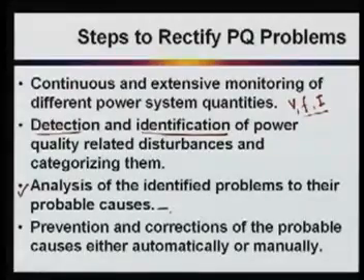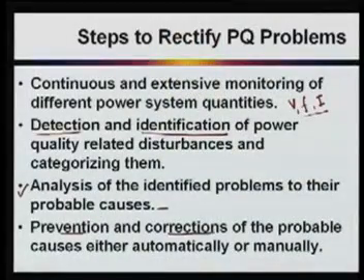Let's suppose you have identified that it is a voltage sag. After extensive monitoring of the voltage, frequency, and the current, it is identified that the problem is your voltage sag. Then you have to analyze your system for what the probable cause was. Was it a single cause or many causes? So we analyze the identified problem to its probable causes. Once you have analyzed, then you can have some preventive or corrective measures.